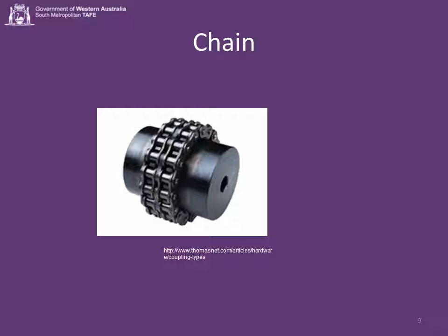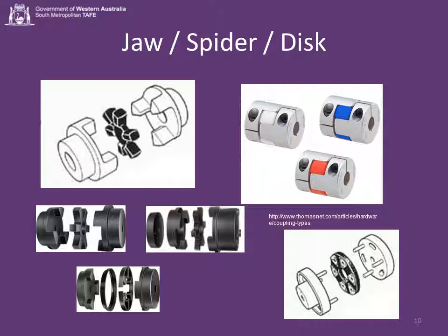Chain couplings are suited to power transmission applications and are used to transmit power up to and into the hundreds of Newton meter range. Angular and parallel misalignment allowances are typically 2 degrees and about 0.5 millimeter, respectively. Typical chain couplings use special chain sprockets and double wide roller chains whose clearances permit the design to operate as a flexible coupling.